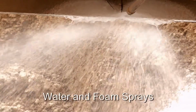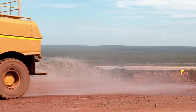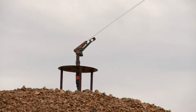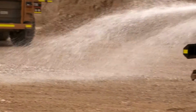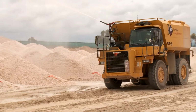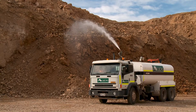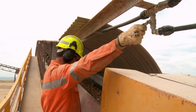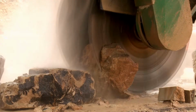Engineering controls, such as sprays of water and foam, can control the amount of dust transmitted to the air. Use water trucks for dust control on haul roads, hosing stockpiles to wet down material transfer areas. Dust suppression products and systems are also effective means to control dust in stockpile areas, haul roads, and work faces. Automated and manually controlled atomizers that emit fine water sprays. Cutting equipment with water jets.